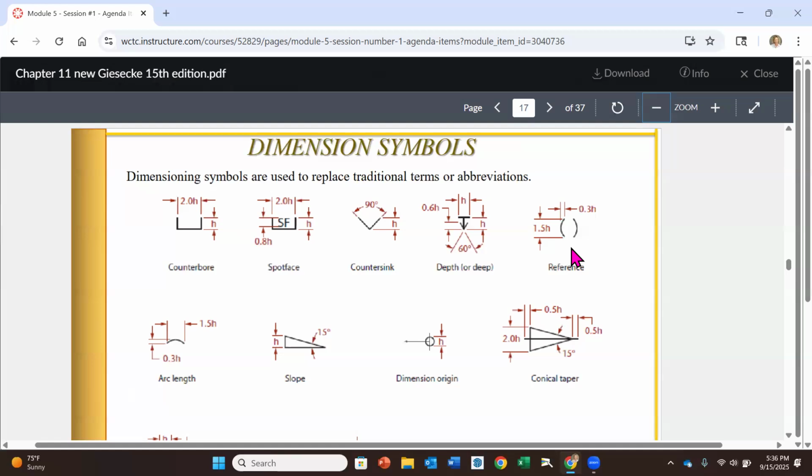If you have drawings that have a bunch of section views, and I mean, literally you could have 8 to 10 on a drawing, okay? And that's not terribly uncommon for complex parts. Well, now if you have the dimension just in one view, but then you're referencing in another view some other things where that dimension would add clarity, you don't want to put it on as another dimension. You want to put it on as a reference dimension. So that is very common, and that would be in parentheses.